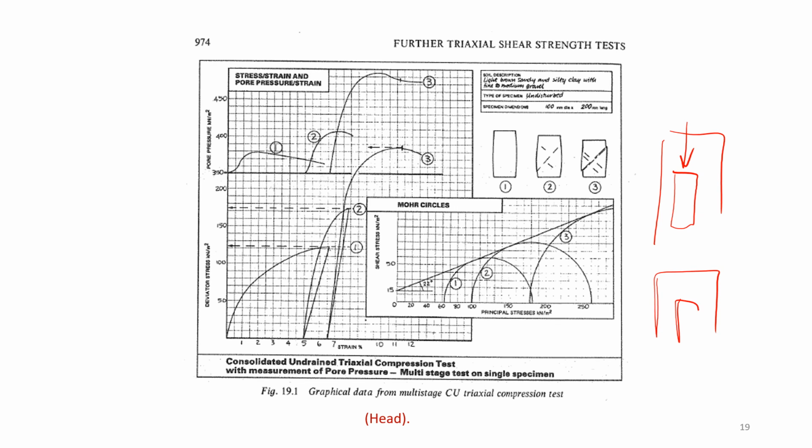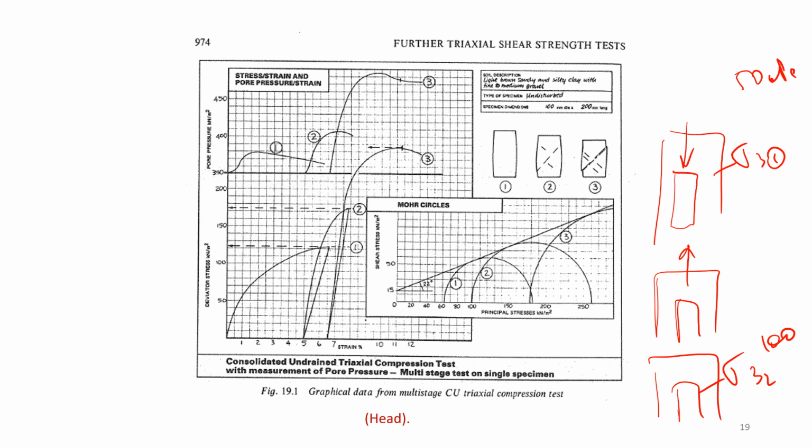unload your loads, go back, and initially you apply sigma 3, 1. That means, let's say 50 kilopascal. When you unload, you need to apply another stress, sigma 3, 2, for example 100 kilopascal, and again start shearing. Again stop somewhere, stop, stop.